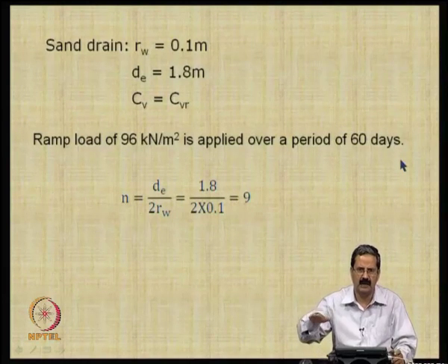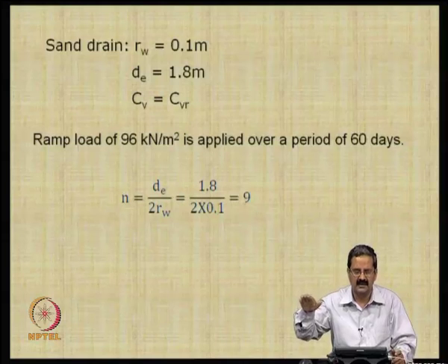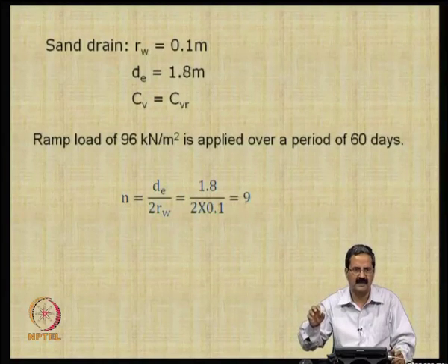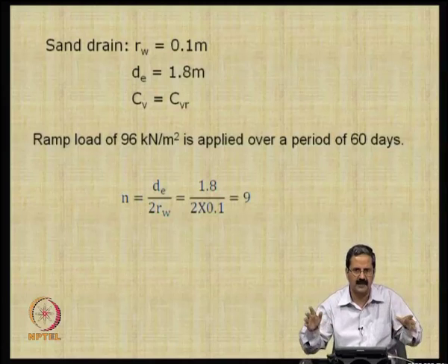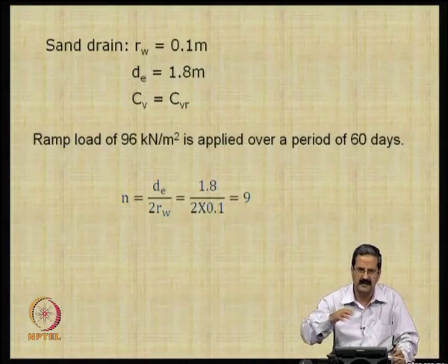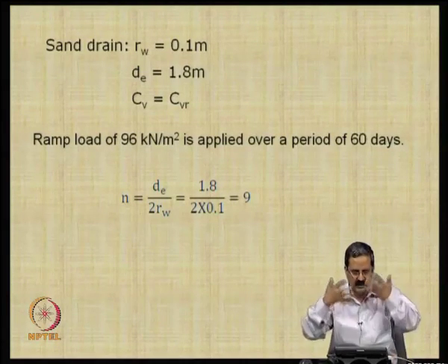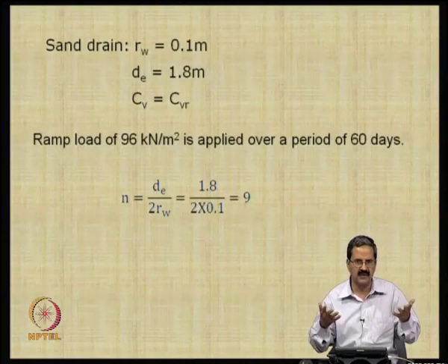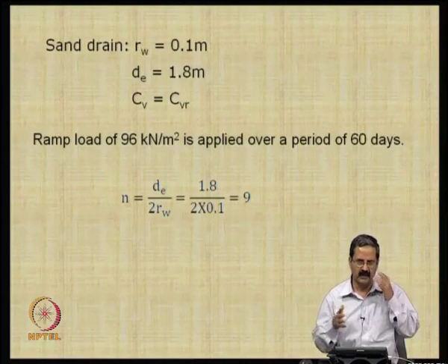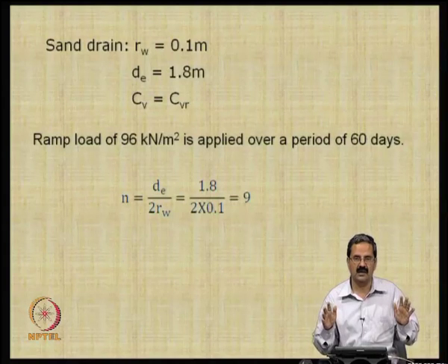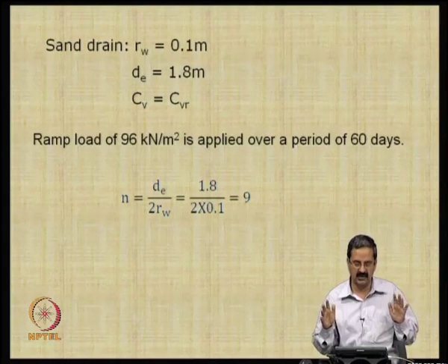Like I slowly apply the load, because in a soft soil area you should not allow collapse to occur. If you suddenly apply the load, there is a shear failure, and then you can't use the area. It is something very bad, it totally collapses, so it will not take any load. That is not a requirement here, that is in fact a dangerous situation.